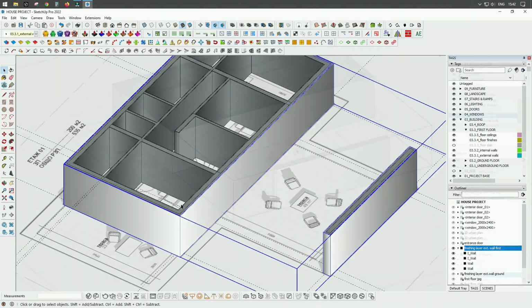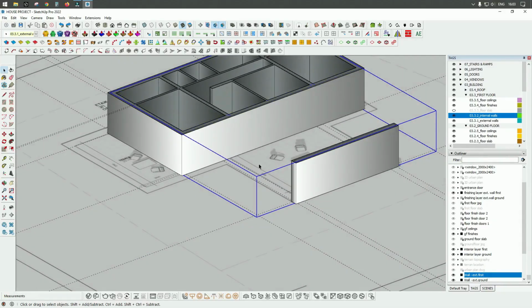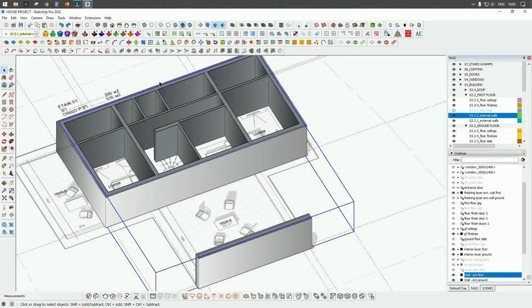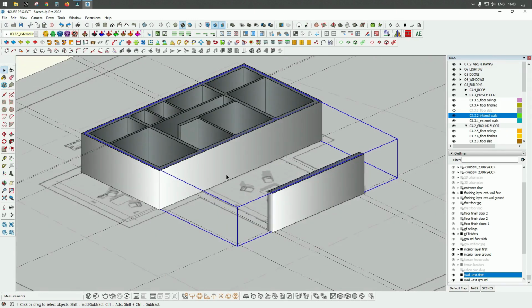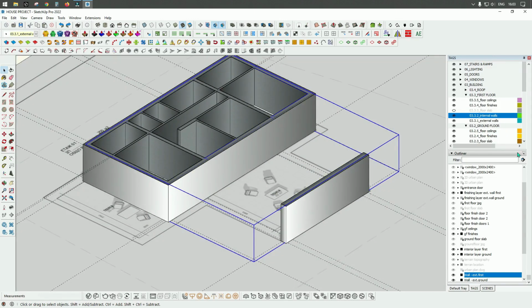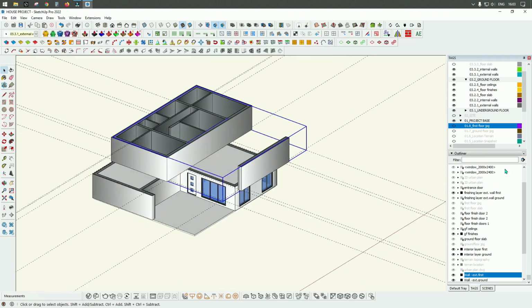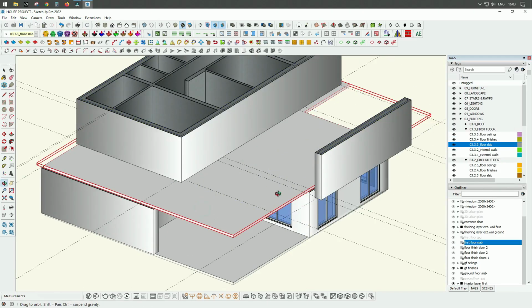for the first floor. Now it's time to adjust our structural slab in order to fix to our external walls for the first floor. And in order to do this very easily, I will hide for a moment our reference file by going in our project browser into the project base, and I can simply hide our reference file, and I will unhide our floor slab. So as you can see,